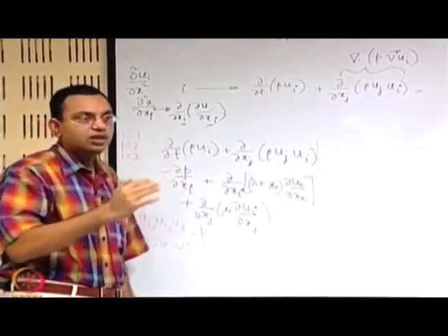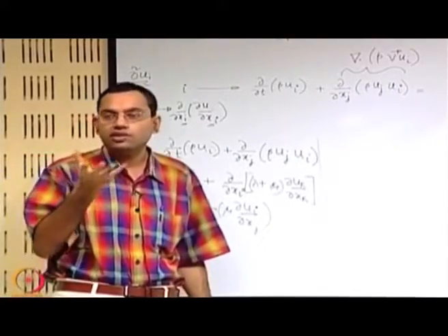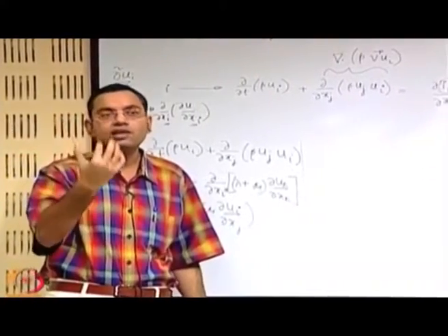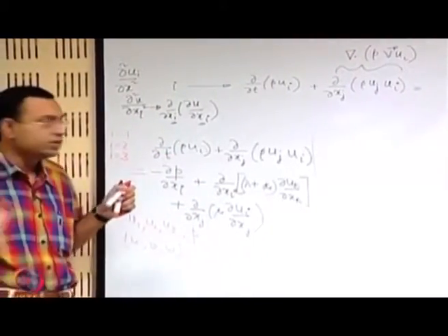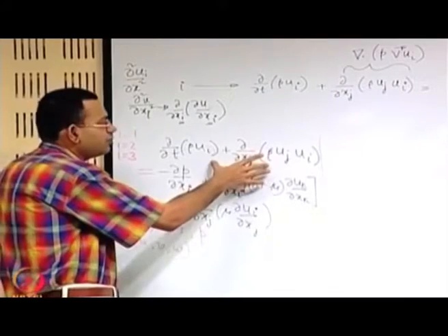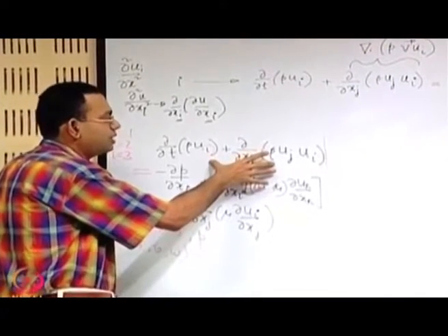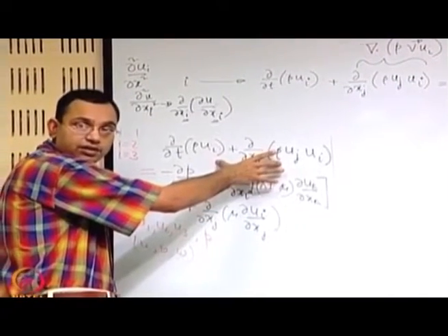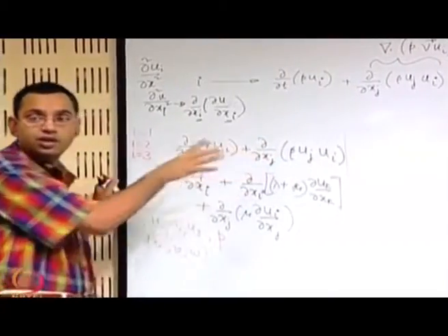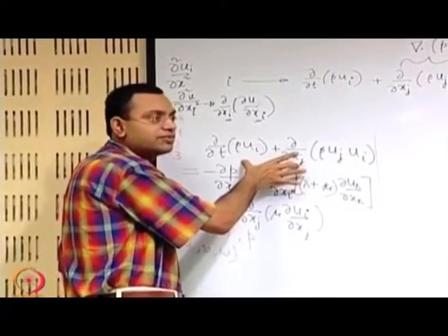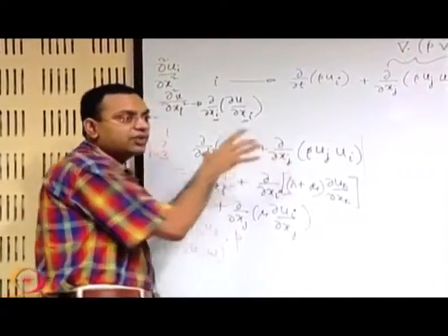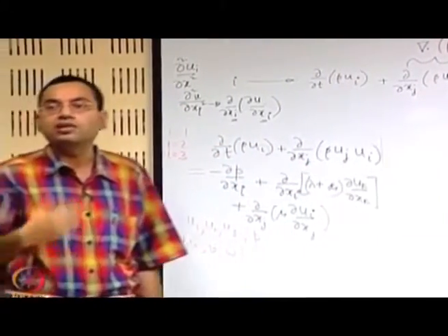We started with the control volume conservation using the Reynolds transport theorem, and we just converted it to its corresponding differential form, but we have not disturbed the form. So this still has come from a conservation principle directly. Now utilizing the continuity equation we will simplify the left hand side further, and that will bring us to the non-conservative form.